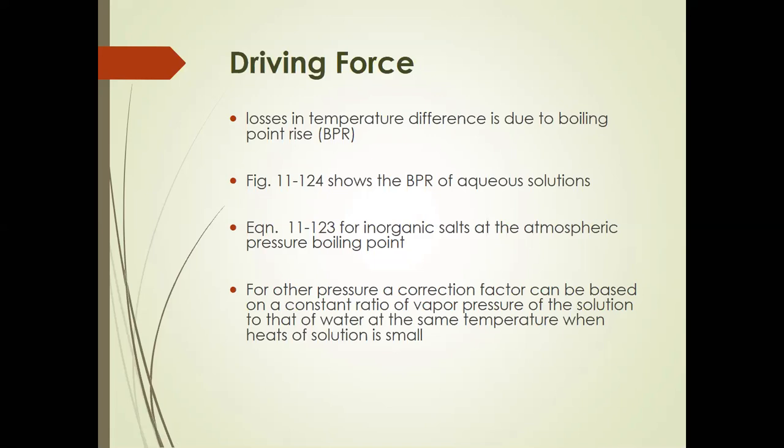Now, in your handbook, you have the BPR of commonly vaporized or concentrated aqueous solutions, and it's found in figure 11-124 of your handbook. I'd like to go to that illustration now. That way I can already explain how you're going to find the BPR or the boiling point of the solution based on that particular figure.